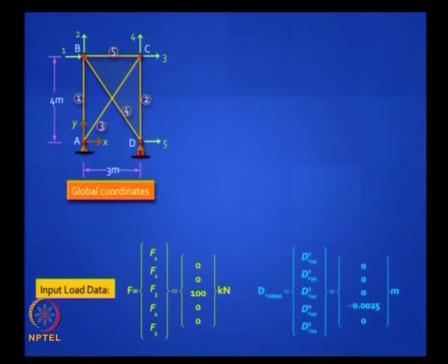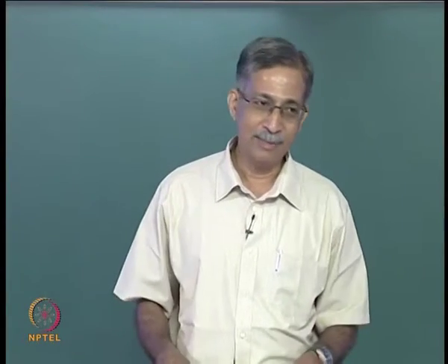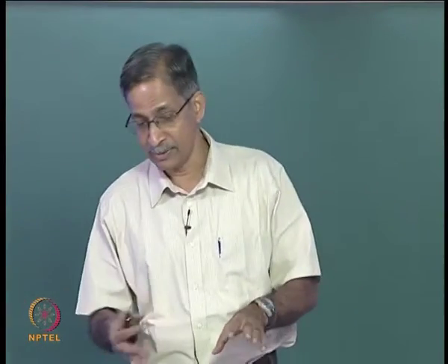That 100 kilonewton will give you joint displacements, certainly you will get d1, d2, d3, d4, d5, but the other load, the indirect load, will add on to the joint displacements, but it will not add on to the internal forces. So it is necessary to be good in structural analysis fundamentals and then use matrix methods only as a tool, otherwise you will not be able to appreciate the solutions that you get.